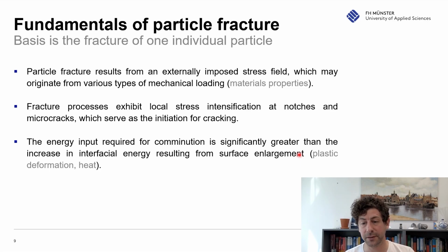Surface energy. However, it's not that easy that I can just say, even with some theories, in another video we will talk about it, make this assumption to say, hey, I know the new surface area, so I just calculate the increase in surface area, and this is the energy I need to crush it. No, because we have plastic deformation, we have rearrangement, we have heat which is generated, and energy goes also into this. So a lot of things happen at one particle, and this is the fundamental of fracture.